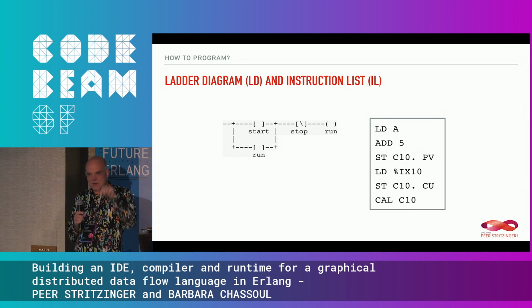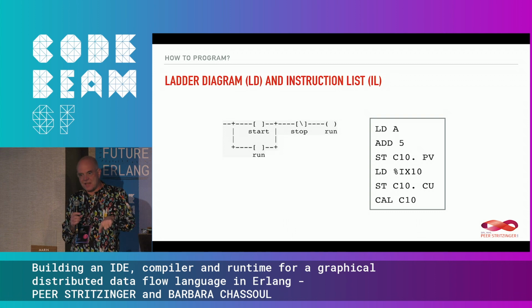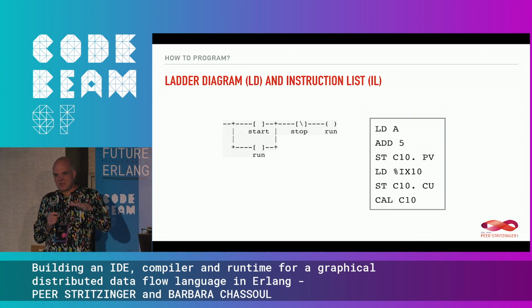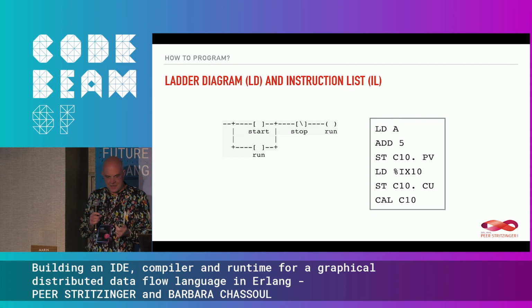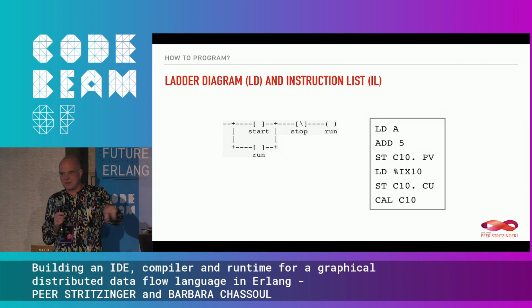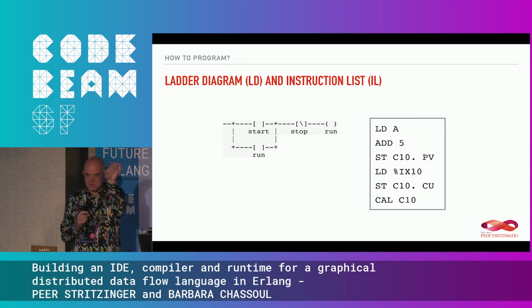And these coils are then connected to switches and switch on or off. When there's a slash inside, that means a not. So it's switched off when the coil goes on. And the coils have names, and the names interconnect these things across layers. So you have multiple layers of these things. That's why it's called a ladder diagram, because it looks like a ladder. And that's what the electricians drew up when they wired the machine.